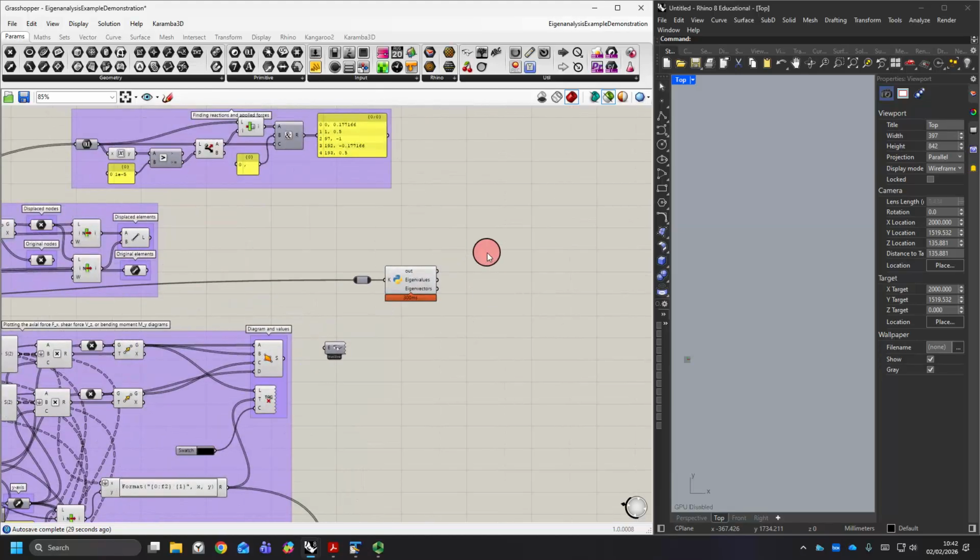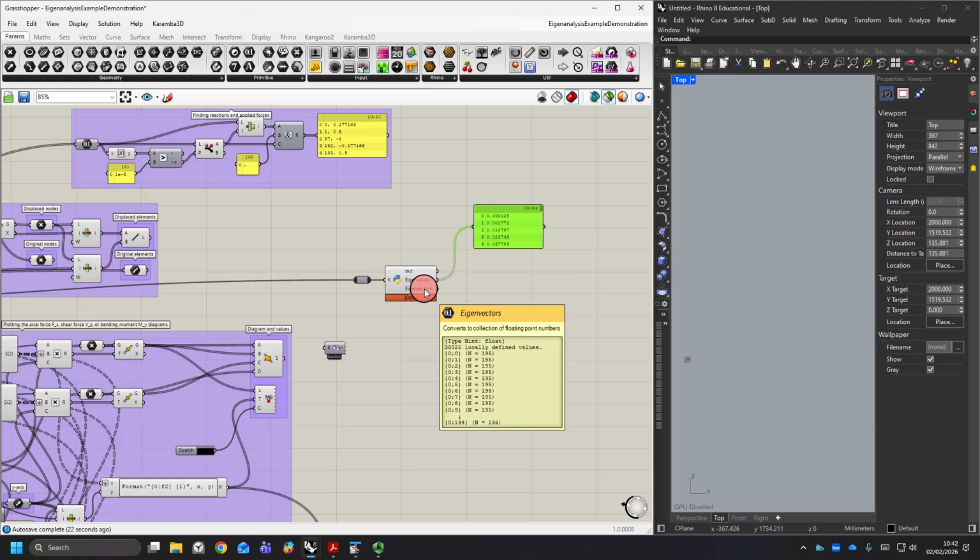So we can obviously just put in a panel for the particular setup that I have, which is still the portal frame. You can see the list of eigenvalues there, so they quite quickly increase, but you can see the lowest ones will help us identify the modes that the structure is most likely to deform in. So we'll come back to that obviously when we get to look at the eigenvalues.